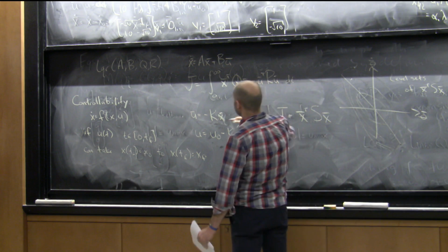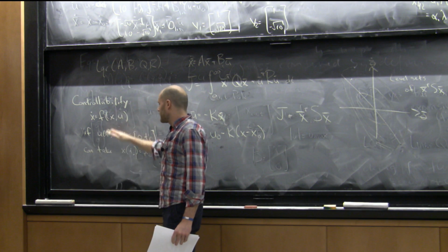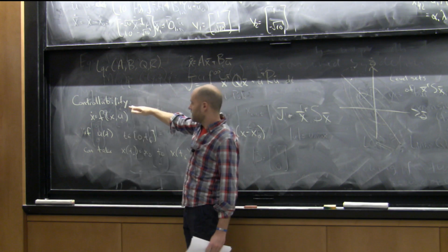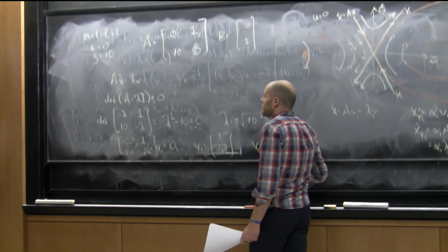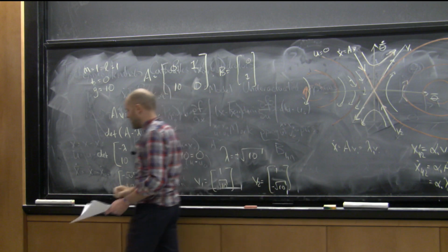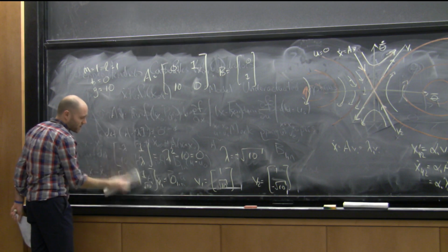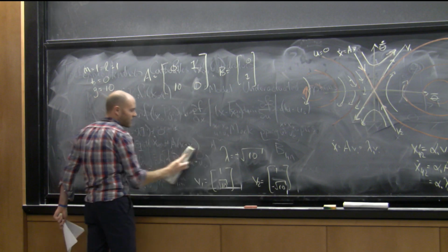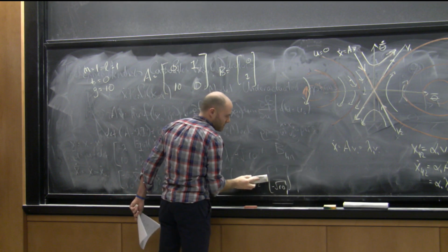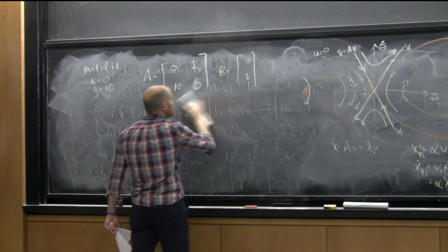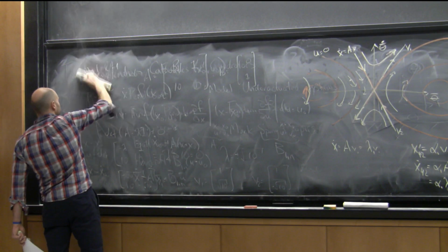Okay, so you can turn the crank on any x dot equals f of x, u around any fixed point and get out some equations and pop it into LQR, and if it's possible, it'll return a solution. That's awesome. It turns out if you care about the manipulator equations, robots, then you don't even have to do all the work of linearizing all the dynamics, because most of the terms drop away magically. A lot of it is because you're at a fixed point. Some of it is because of mechanics or the laws of physics or something, but it works out that linearizing mechanical systems is easy.